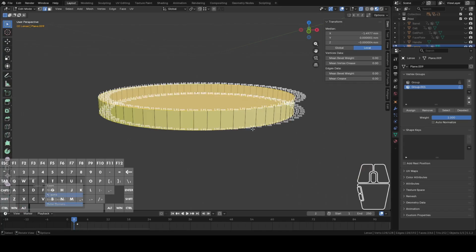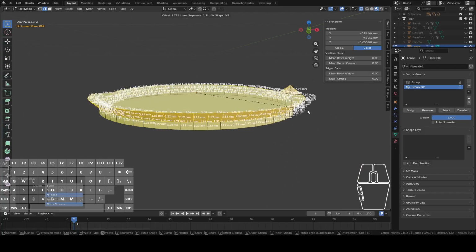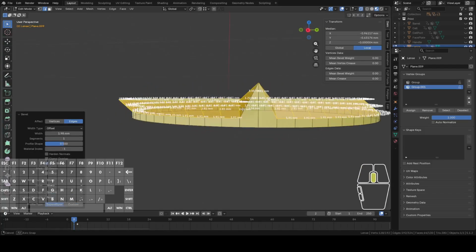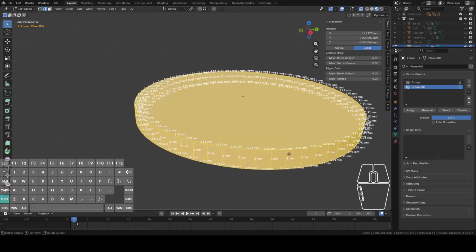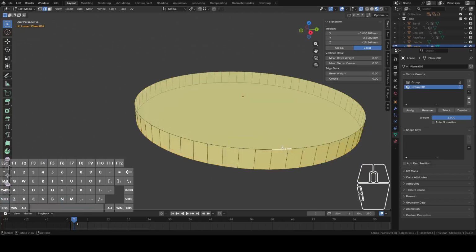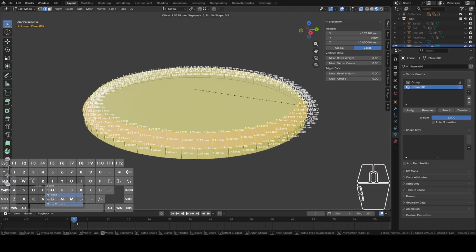You're not gonna see it, but it might help fit it in a little better. Hmm, should actually be fine. I just want to bevel this side. Let's bevel this a little bit. Oop, some weirdness over here. Let's hit A and then Shift N to recalculate our normals, and then try that again. There we go.